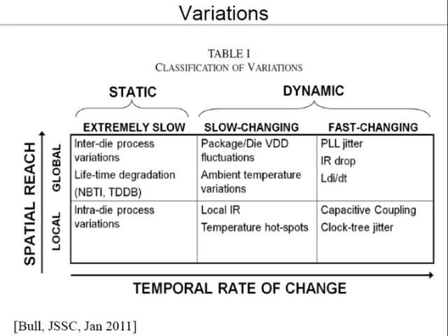When changes are slow, you can think of circuitry which will track it and compensate for it. If it's a static change, if you can measure once, you can compensate for it, for a static distance. If it is a slowly time varying change, you can have some circuitry which measures and keeps adjusting, as long as the circuitry which is measuring and adjusting has a speed much faster than the rate of change. So that is basic control system stuff.